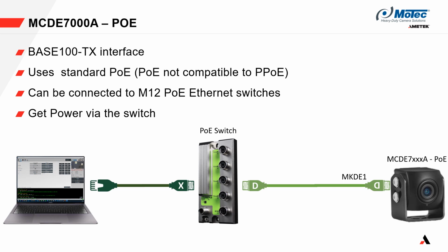Please note that the PoE and passive PoE are not compatible with one another because passive PoE does not use the handshake which PoE switches use to detect whether a device needs power or not.